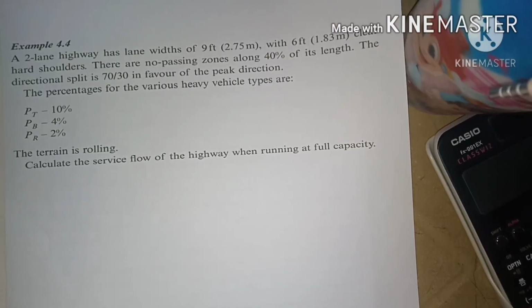Finally, since yung design hourly volume natin is a two-directional flow, tulad ng AADT, the flow of peak direction is estimated by multiplying it by a directional factor D. So, DDHV is equal to K times D times AADT. Para mas maintindihan natin to, let's try an example. And for this problem, pakibasa na lang. You can pause the video para mas mabasa nyo maigi yung problem.